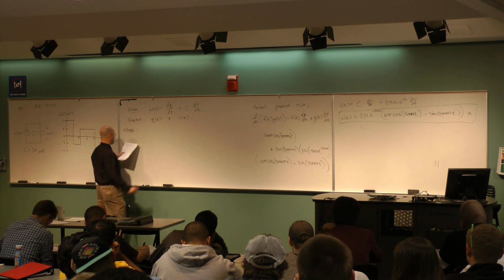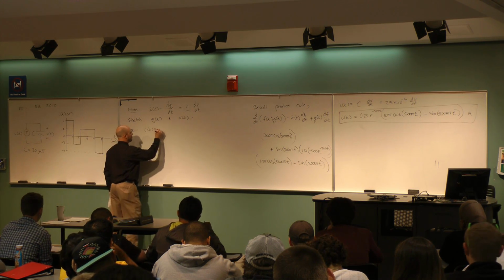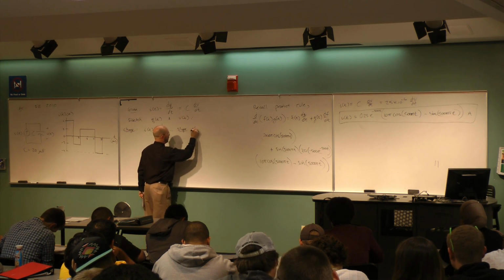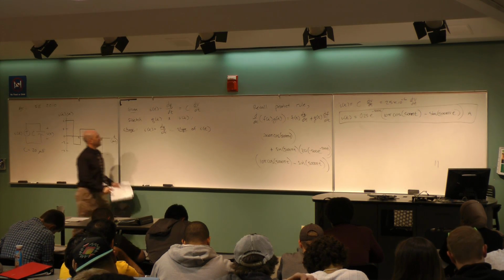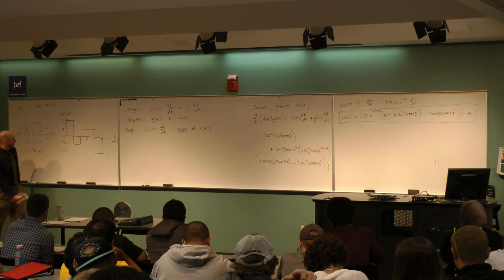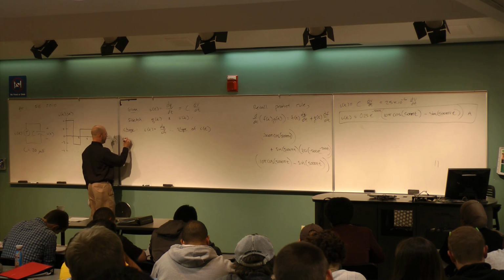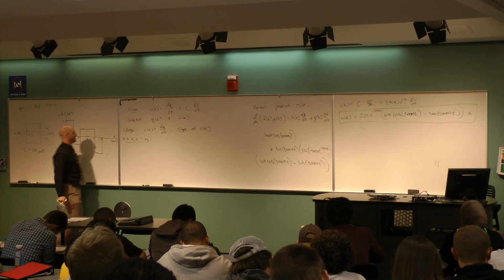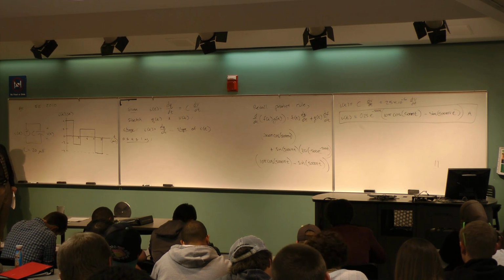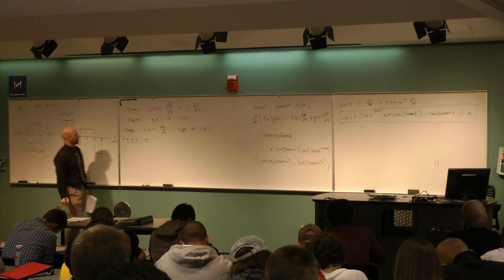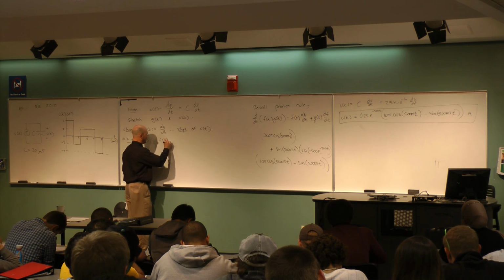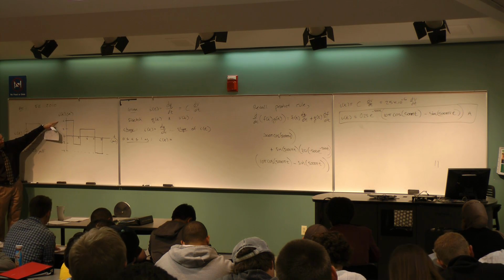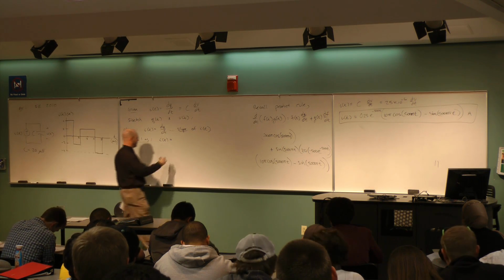Starting with the charge, knowing that i(t), which is given, is dq/dt, the slope of q(t), what can we get in each interval? For example, the first interval, 0 ≤ t ≤ 1 millisecond. What's i(t) equal to? Is i(t) 0? 4. 4 amps, right.